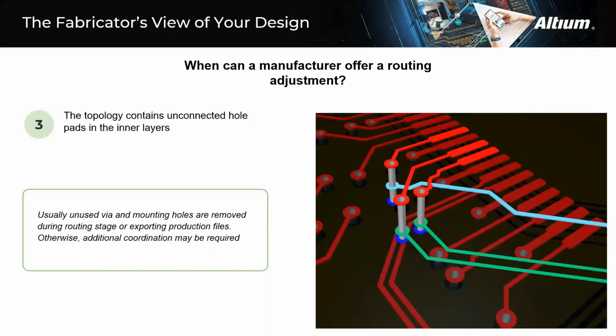There are two options for working with unconnected pads. One is a special function when doing the placement and routing. The other is a setting when generating Gerber files. The first one is used to leverage routing, removing unconnected pads, providing more space for routing. The second one usually deletes remaining unconnected pads by default when exporting the files.